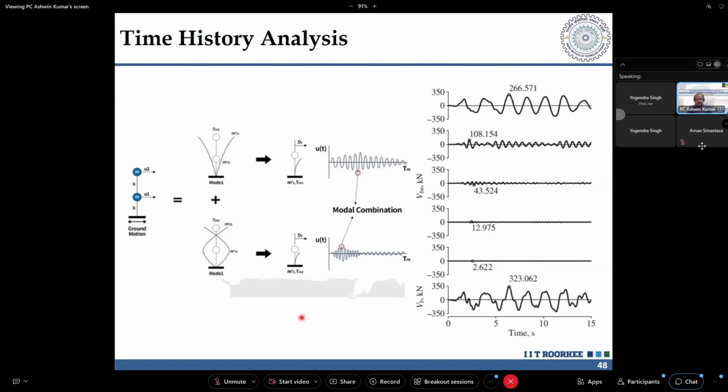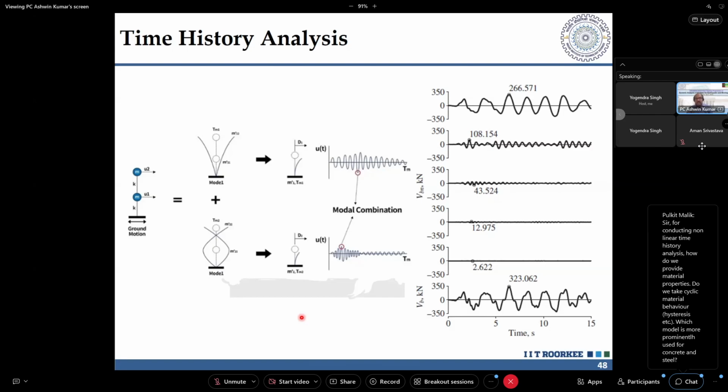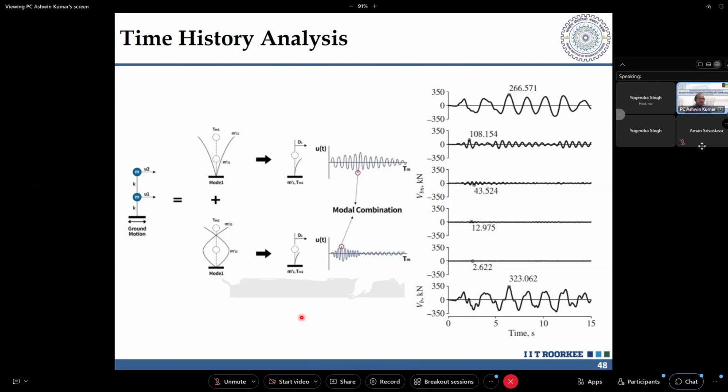But once you see DSHA analysis, PSHA analysis, selection of ground motion might also be a problem for you. Ground motion selection is a very difficult aspect. Once you do it, you will understand, okay, it's better I choose this method or that method, whichever is appropriate, and then you will get an idea of how far it differs. Once you take up a problem, do that problem and understand the results you are getting. If the structure is simple, both methods might give you the same answer.